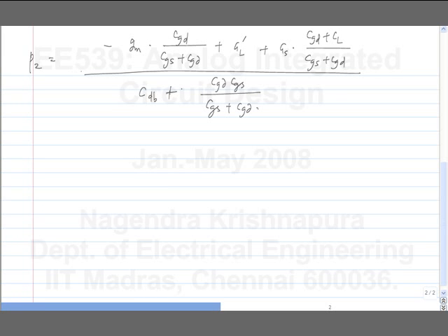If it behaves predominantly like a first order system, it's the product of the pole and the DC gain. What is that product? Approximately. We will consider a scenario where CGD is dominant. GM by CGD. It says the answer is GM by CGD. Is that correct?